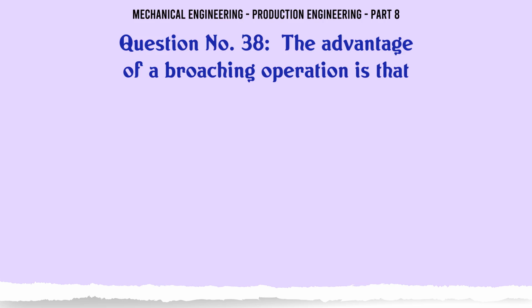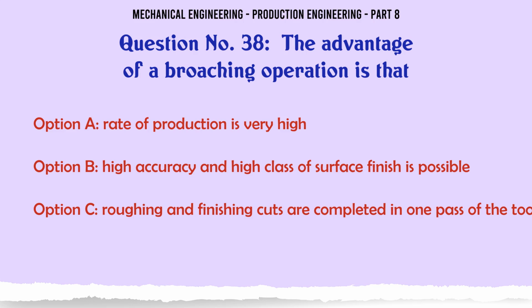The advantage of a broaching operation is that A. Rate of production is very high. B. High accuracy and high class of surface finish is possible. C. Roughing and finishing cuts are completed in one pass of the tool.